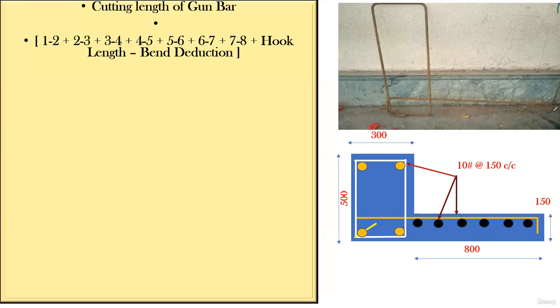If you don't understand, I'll start like this. This is point number 1, so it is easy for me to prepare the BBS. This is point number 2. Wherever there's a change or a bend, I'll take it as one point. So 1 and 2, this is my third point, this is the fourth, this is the fifth, this is sixth, this is seventh, and this is the eighth one. Got it? This much you understood, so I've written the same thing.